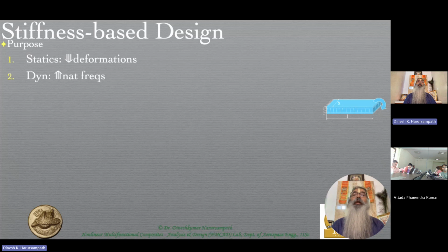If it is so, then typically you can end up with resonance, and these have resulted in some really disastrous accidents for various vehicles, in particular helicopters, through what is known as ground resonance. Just a helicopter on the ground with its main rotor switched on, the power to the main rotor, and therefore it's rotating, and suddenly it breaks apart and falls. It has not even taken off.